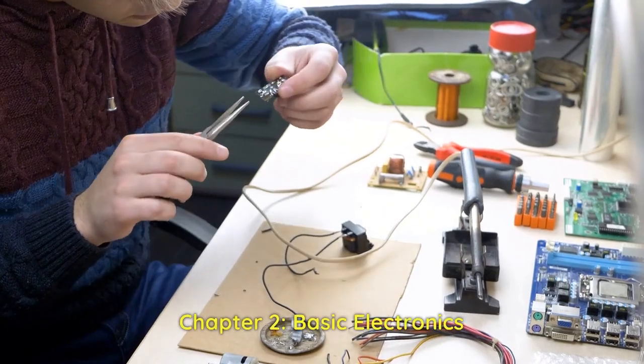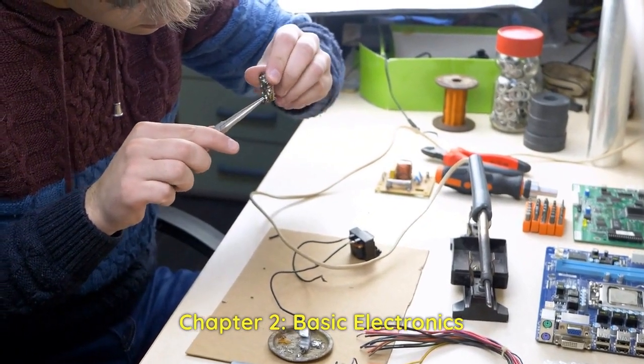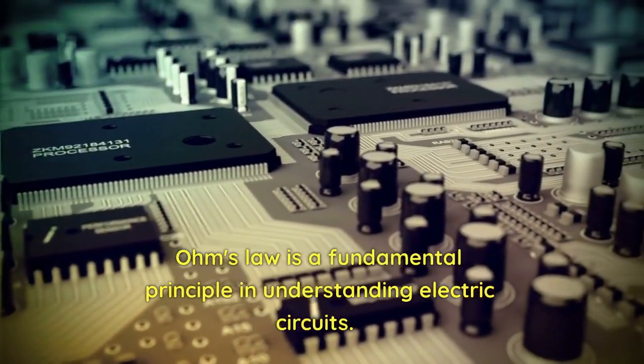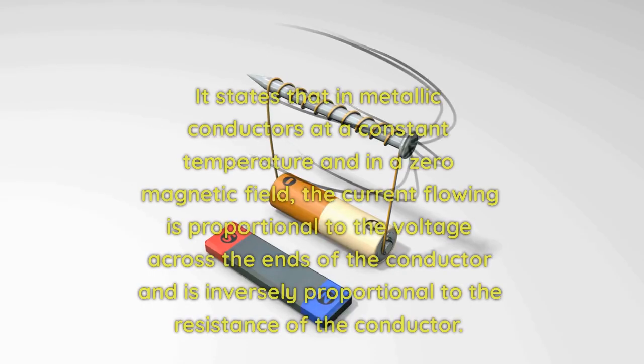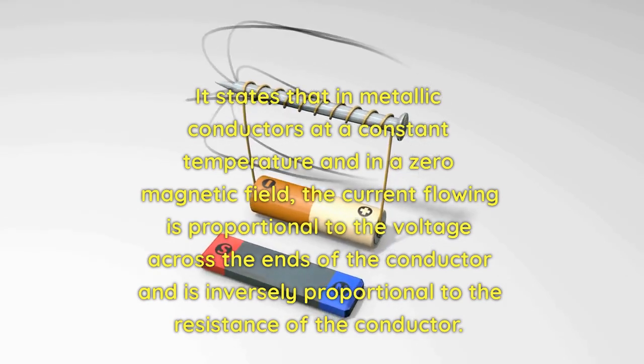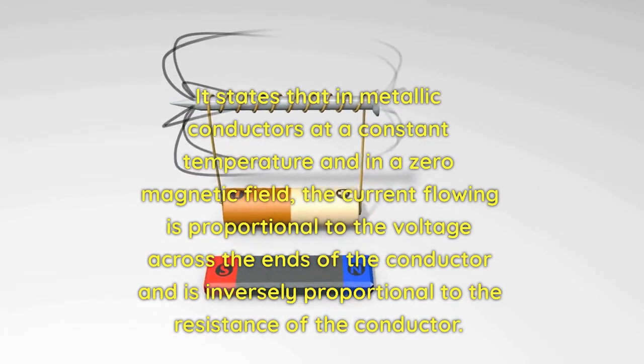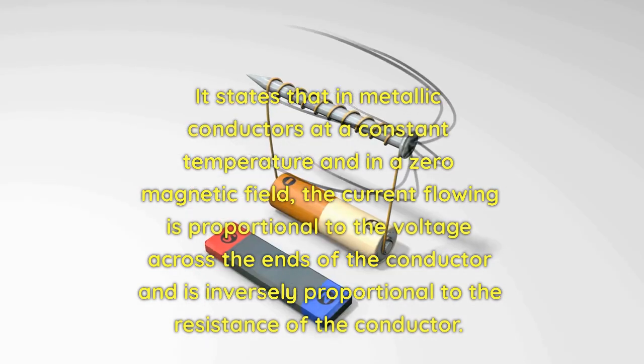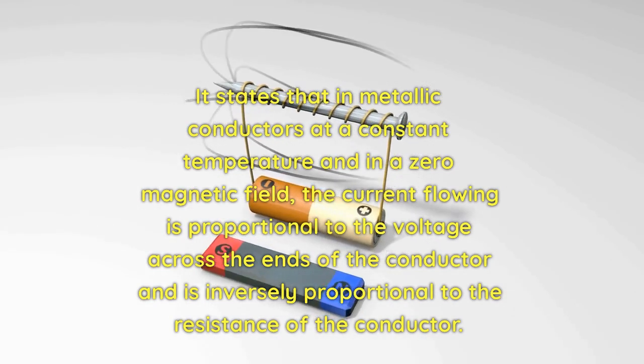Chapter 2. Basic Electronics. Ohm's Law. Ohm's law is a fundamental principle in understanding electric circuits. It states that in metallic conductors at a constant temperature and in a zero magnetic field, the current flowing is proportional to the voltage across the ends of the conductor and is inversely proportional to the resistance of the conductor.